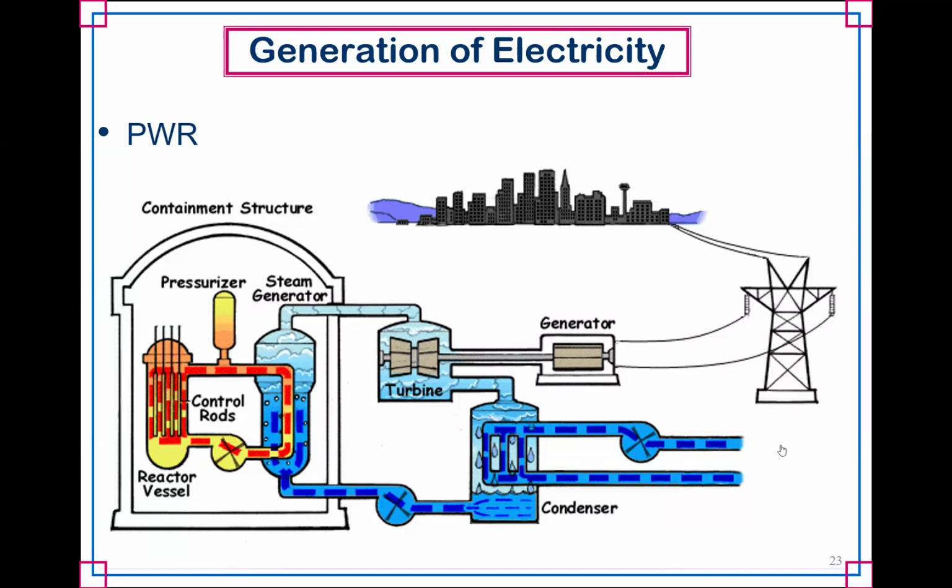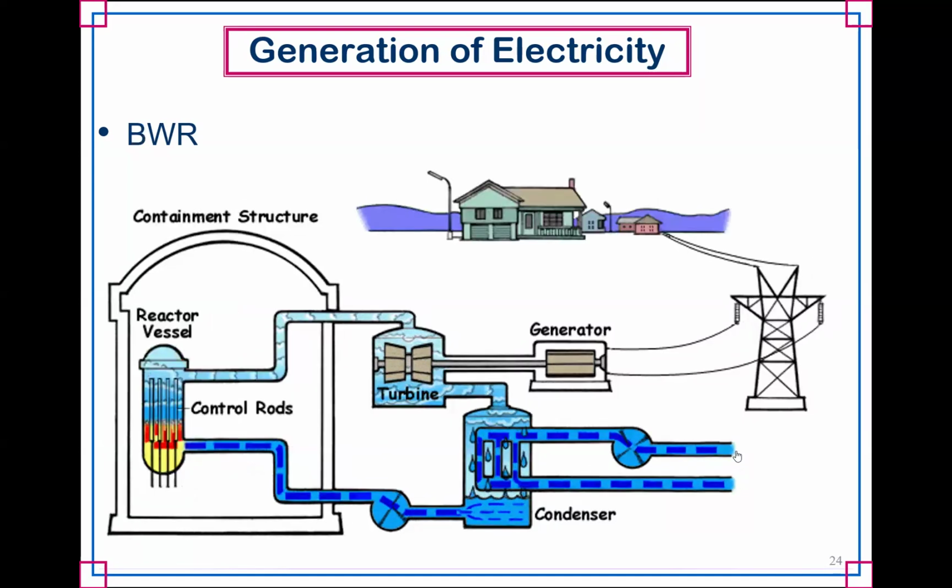And interestingly enough, in this pressurized water reactor, you have to have two failed systems before you release any radiation to the outside world, because you have to have the condensate heat exchanger fail before you actually start getting radioactive material out there. So not only would you have to have the steam generator, but you'd also need to have the condenser heat exchanger have some failures.